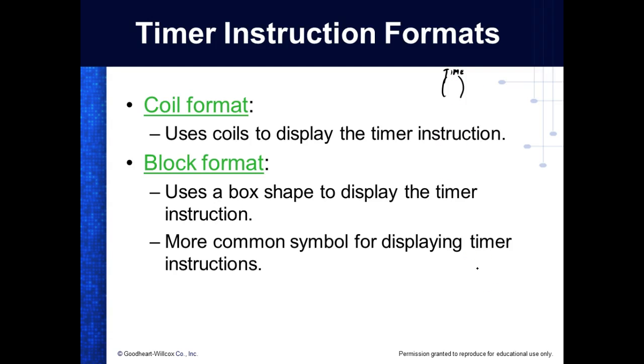More and more, they're going to a function block format for timers, and that's what RSLogix does. So we're going to have a block for a timer. We're not going to have a coil. I'll try to show y'all that in RSLogix next class. So we're going to use the function block format. It uses a box shape to display the timer instruction, the more common symbol for displaying a timer instruction.